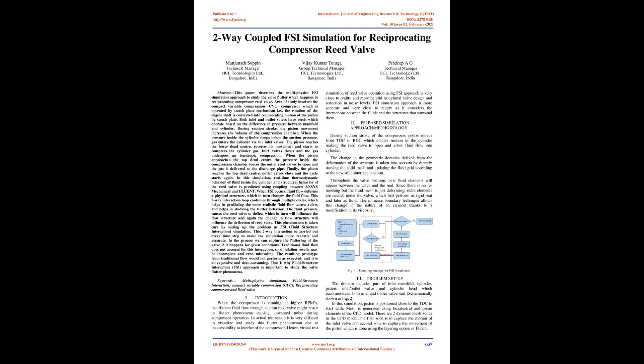When FSI occurs, fluid flow deforms a physical structure, which in turn changes the fluid flow. This two-way interaction loop continues through multiple cycles, which helps in predicting the more realistic fluid flow across valves and helps in studying the flutter behavior. The fluid pressure causes the reed valve to deflect, which in turn will influence the flow structure, and again the change in flow structure will influence the deflection of reed valve. This phenomenon is taken care of by setting up the problem as FSI, fluid structure interaction, simulation.